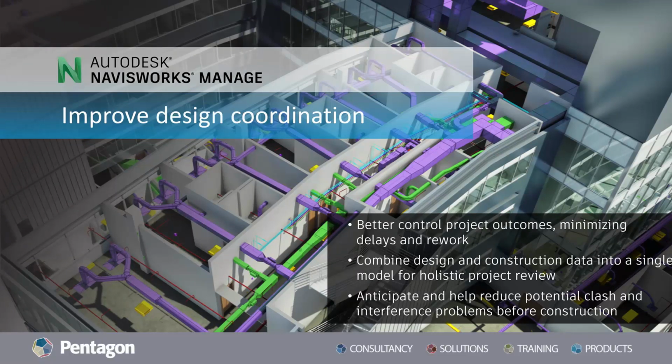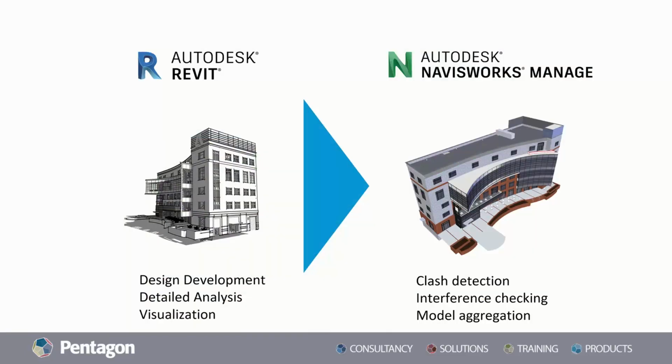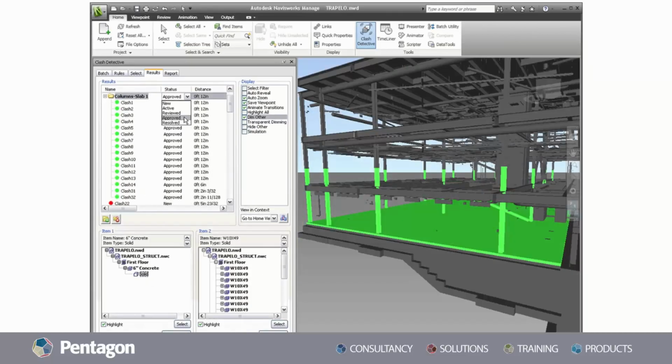Navisworks then. So Navisworks is used to complement 3D design packages. We're looking specifically at Navisworks Manage and some of the tools and commands you can do in there, but there is also a Navisworks Freedom, and what Navisworks Freedom is actually just a viewer. So it allows you to open up different file types and stuff like that, but you can't actually do anything in it. But sticking with Manage at the minute, you can see again here, it ties directly into Revit basically. It accepts not just Revit files, but almost any type of file. And what it's used for is really to coordinate the different disciplines, the different models all together into one file and one project.